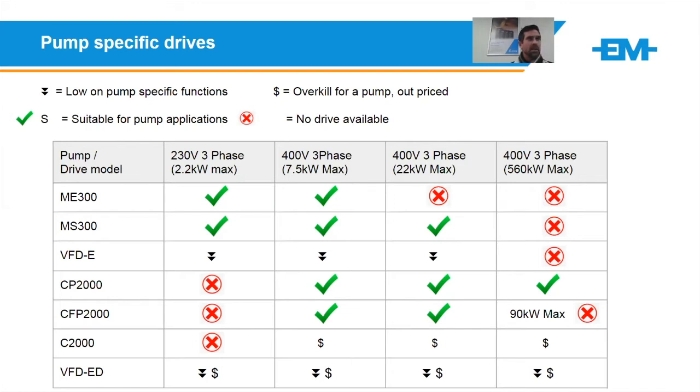You could also add Ethernet cards onto the drive and talk Ethernet back to an HMI that supports that. That's another option. But right out of the box, the RS485 to the drive really works fantastic. We do it quite often.